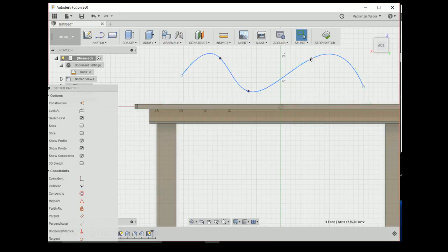And so now you can actually drag these points around, and when you double click on it, this green thing becomes available, and that will allow you to move it up and down. If some of these tails aren't visible, you can go into spline settings in your options and set it to show these tails. But that's one of the more complicated sketch tools. They're fun.